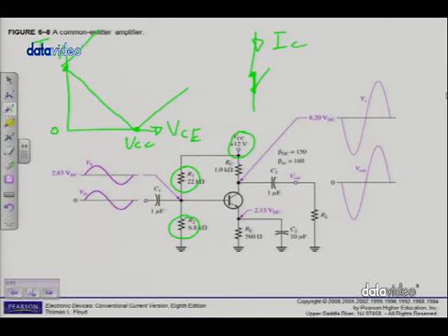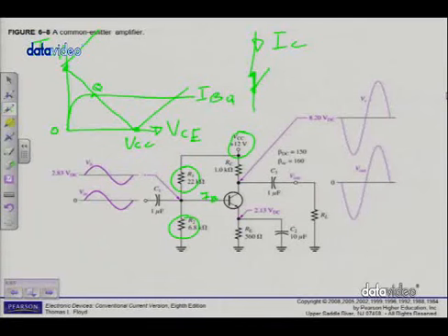Okay, so because I've seen, if I bias the circuit, in this case with a voltage divider bias, to get a certain IBQ, it just means it's the base current for the Q point, because there's my Q point. So this is what I have here at this stage with no signal still there. I can see that my transistor is already on. Now it's ready to amplify.